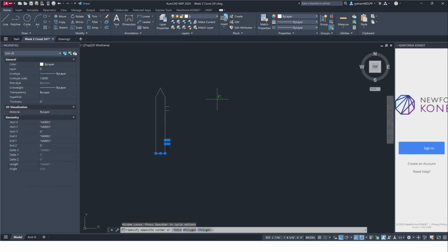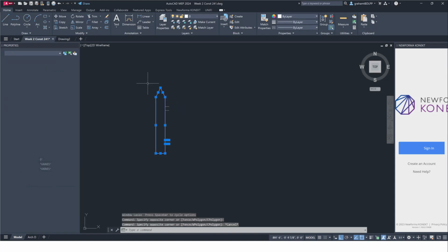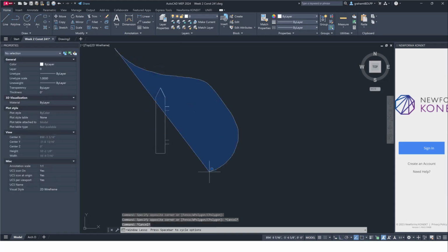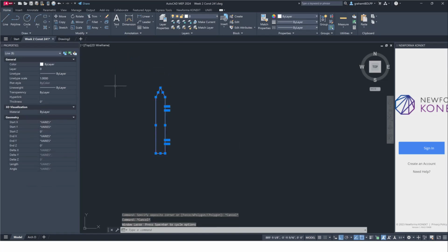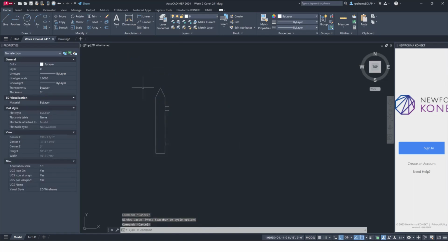And it's saying, hey, I'm going to select wherever this mouse encompassed. And maybe it grabs what you want, but a lot of times it's just annoying. So instead of clicking and holding, just click once and drag your mouse, and you'll have a selection window. Okay, and the selection window keeps it rectangular. It's not going to go all funky.